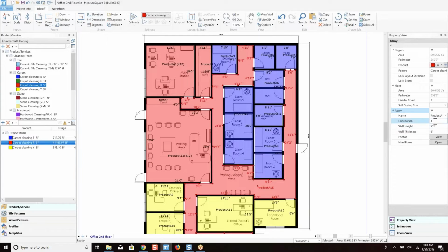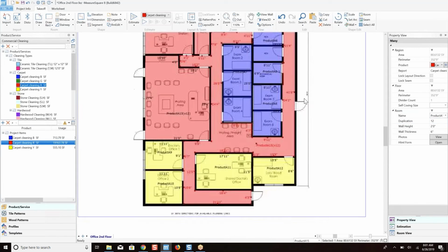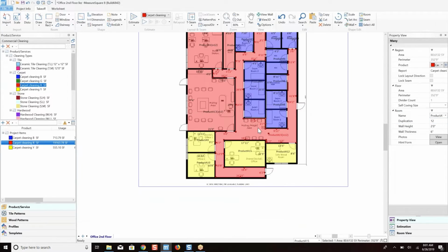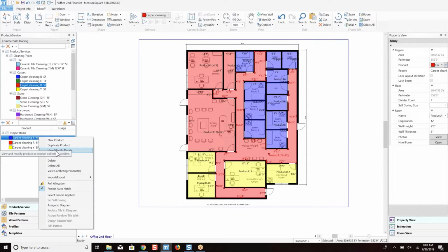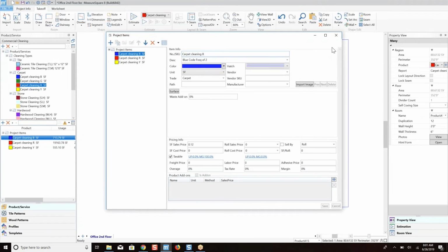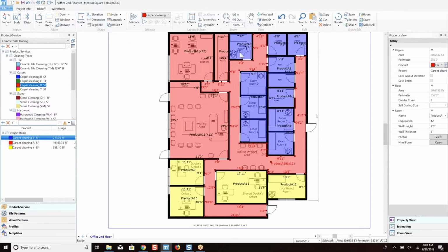Click on the hallway. I can actually just add a 2, that's 12, hit enter as an even quicker shortcut. Now, it looks like I got all my red ones done, and right click on blue to double check my frequency of 2. So now I can just click on the blue rooms, hit 2, enter, 2, enter.